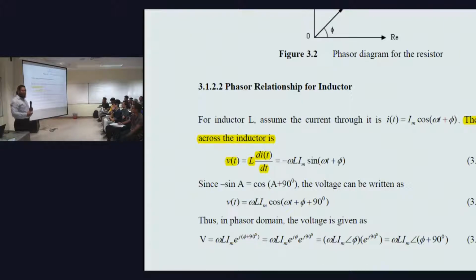Now you are in a position to know the impedance of an inductor, because you know the current through the inductor and you know the voltage across the inductor. So how can you get the impedance, which is equivalent to resistance? Can you tell me how? Go back to Ohm's law. I is equal to V by R. In other words, R is equal to V by I. So you have V, which is this. You have I. Can you derive the impedance?